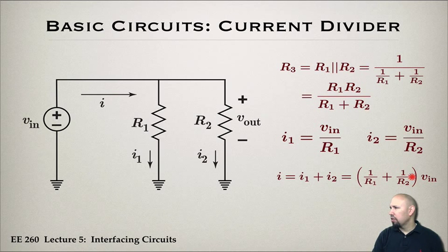If you notice what this looks like, this is actually the inverse of this, which is what we saw earlier as the two resistors in parallel. So this is the conductance of this resistance. That's why two resistances in parallel combine this way: you're summing their conductances, and when you convert that back to a resistance, we get that formula.